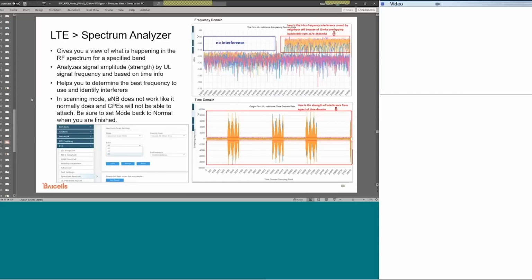Okay, so this is one of those features that's available on the Intel platforms. Because with Intel, we can read the IQ level, something we can't do exactly with Qualcomm. This is one of the features on some products where we do have a built-in spectrum analyzer. You will configure it, and it will be using the LTE stack, but it will be reading the IQ data in all of the uplink subframes.